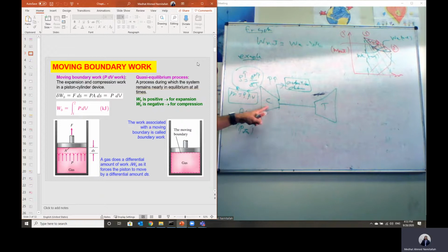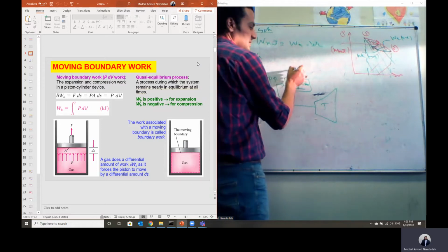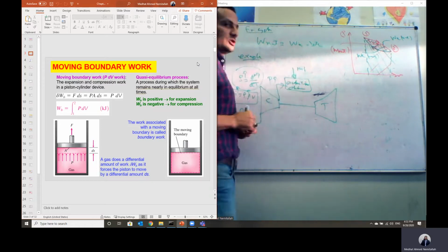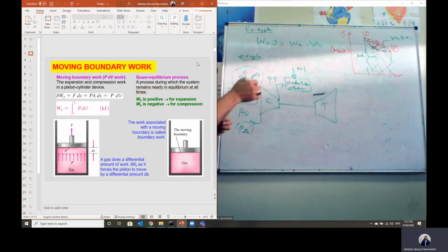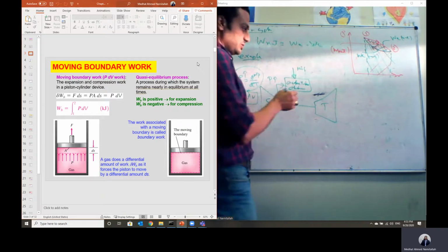So we use the compressor to compress the air to a higher pressure. First of all, it compresses the air to the pressure of the combustion chamber, and compressing the air raises its density, and it also raises the mass flow rate of the air. Then for this combustion chamber, by raising the mass flow rate of air, we can give more mass flow rate of fuel, m_fuel, then we can burn the air with the fuel in the combustion chamber.